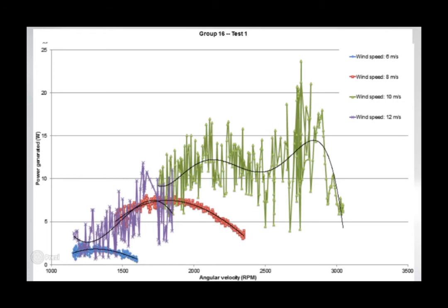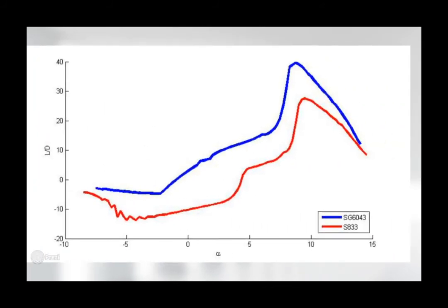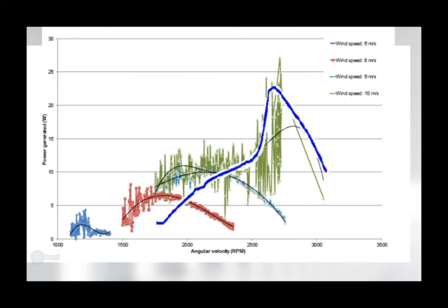Therefore, to maximize power, we had to twist the blade in accordance to the alpha L/D max of the airfoil section, facing the local velocity. In doing so, coupled with the nature of the main airfoil section, SG6043, having a sharp lift-drag curve, this caused a large performance drop-off away from the optimum RPM, thus explaining the power spikes we saw on the power RPM graph.